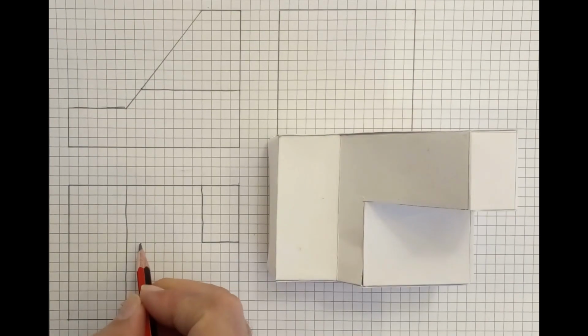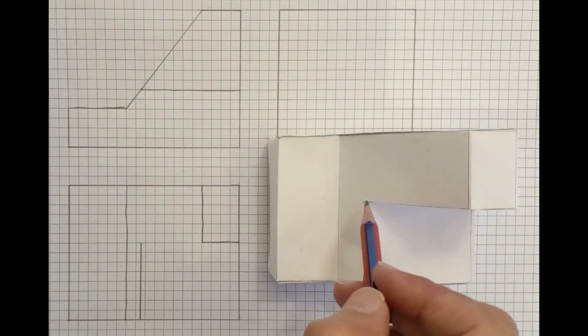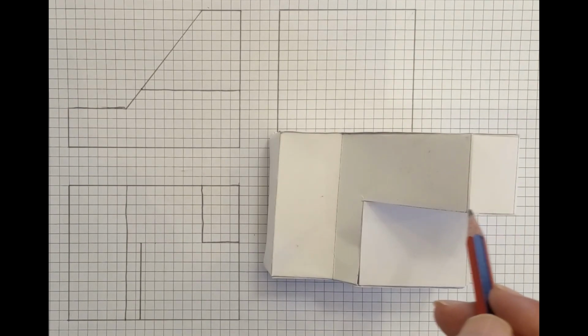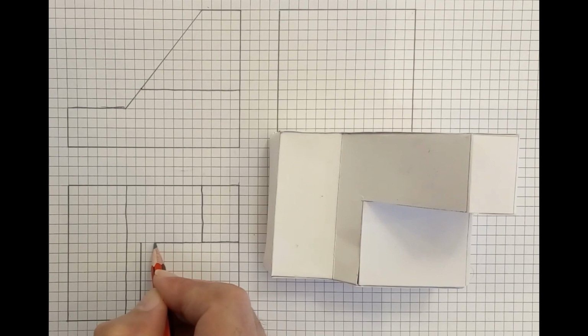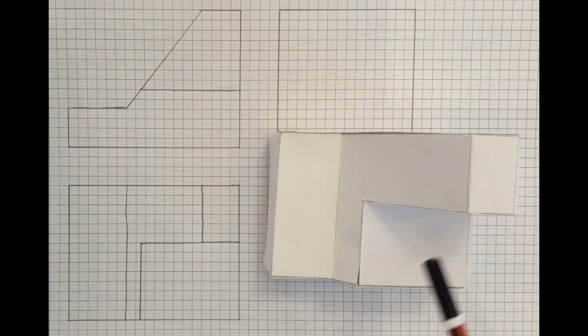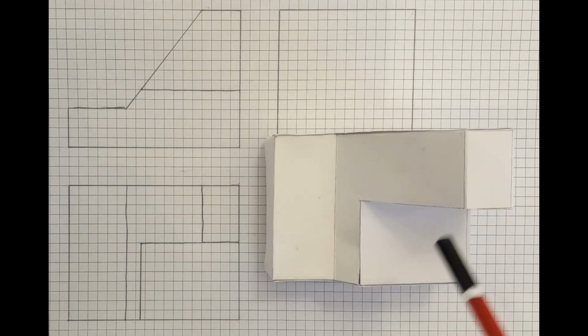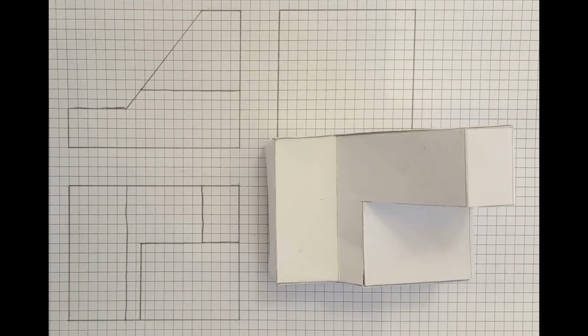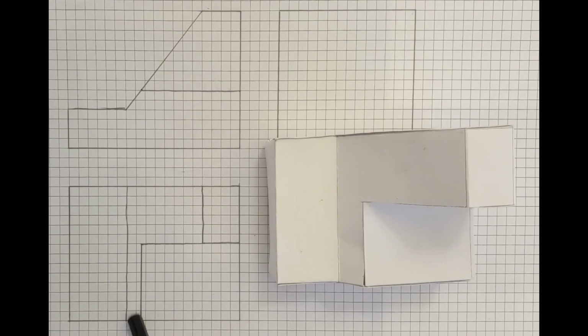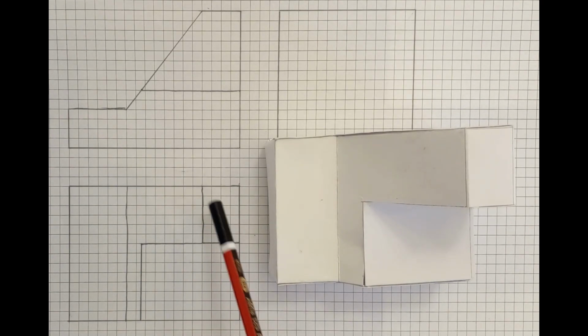But why did I start from this point? Simply because this edge is the extension of this edge. So I will extend this line like this. Now I finished this rectangle. Once I finished these 2 rectangles, this shape is generated. So I don't have to find the dimension of this L shape. It is a result of drawing these 2 rectangles. Now I finished the top view.